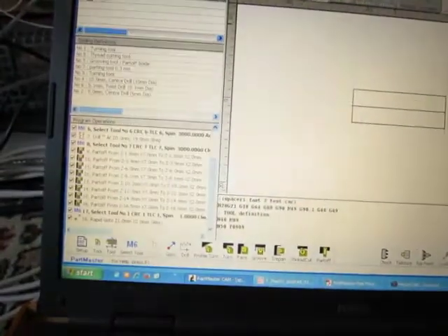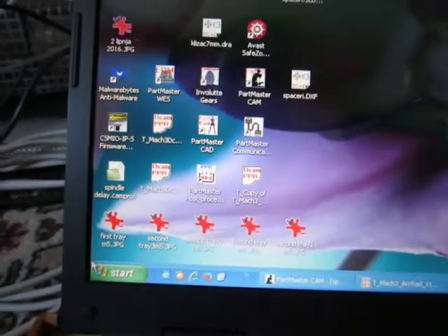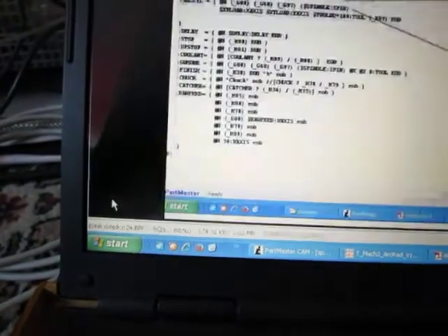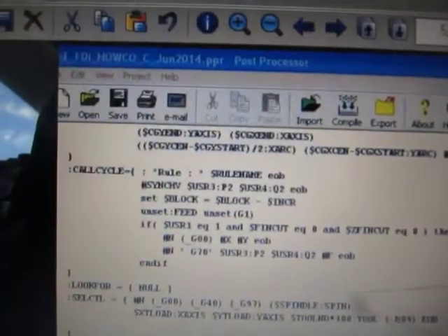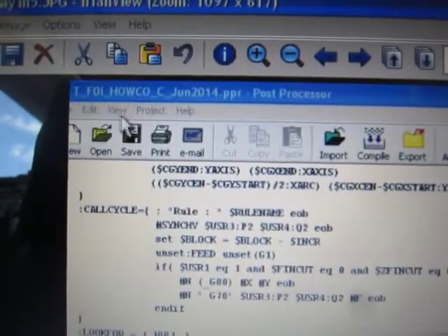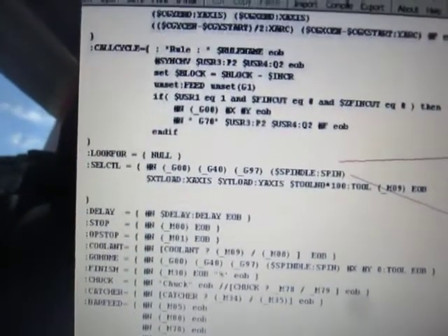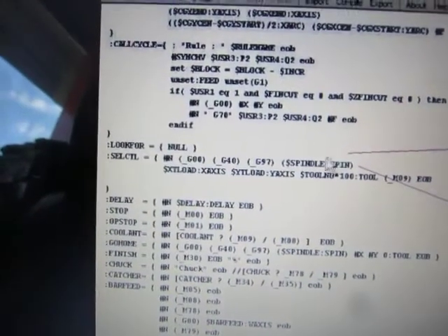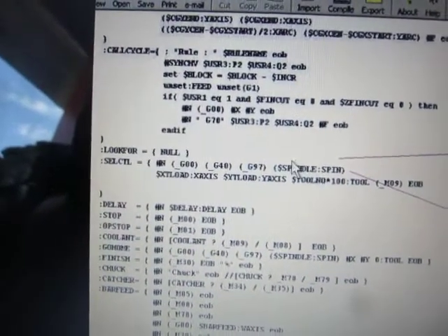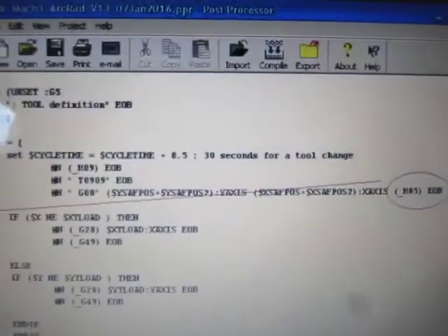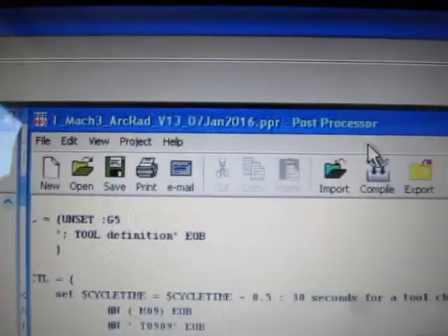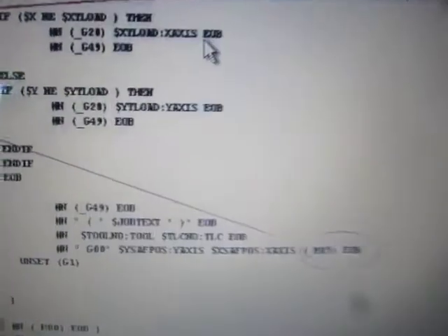And this is the post processor. My first try to adjust the post processor: I took this one and thought maybe I need to copy paste this part here instead of M05 on the post processor that I'm using. But that did not help. It was the wrong place.